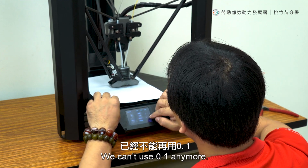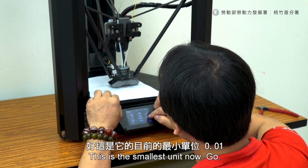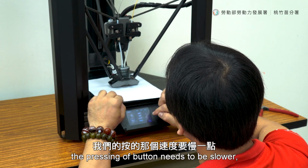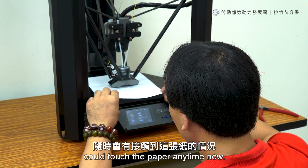We can't use 0.1 anymore. We need to switch to 0.01. This is the smallest unit now. Go. Getting down at 0.01. Now the pressing button needs to be slower because the nozzle could touch the paper anytime now.